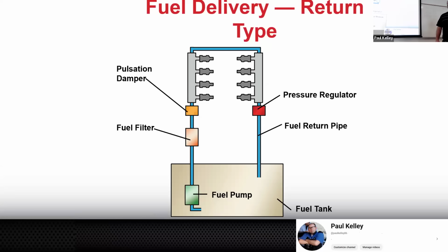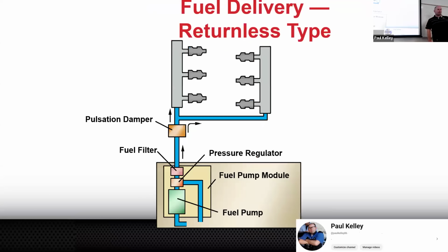That's part of troubleshooting. Here's the new design. This is going to have a longer lasting fuel pump. Because look, and there are even newer designs, FYI, but the fuel pump is going to suck up the fuel. It's going to push it up. The fuel pressure regulator, wait a minute, that used to be up here. Now the fuel pressure regulator is right after the pump. So the pump is still kind of working as hard as it can, but rather than pumping it all the way up and around and over and down, it's just like, you know what? If you're at 51 PSI, I'm just going to compress a spring and dump it right back in the tank. It's not having to pump it as far. I would say it's a little easier on the pump.